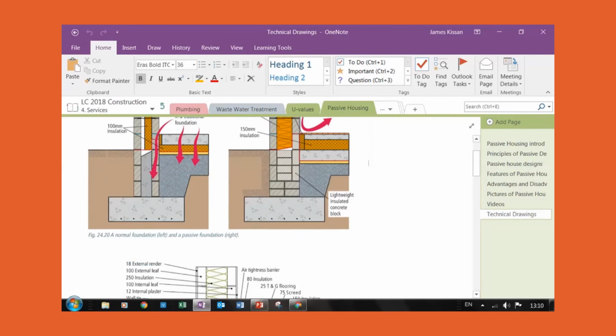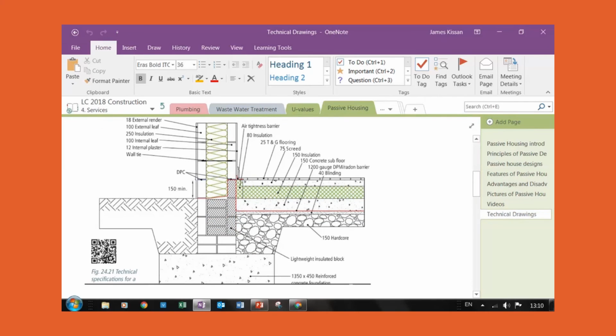Now, the last couple diagrams here are all showing all this detail. Now, these are all in your construction book. So what we have here, and it could come up in an exam that you're asked to do this. Now, what you have, insulation, you have levels of insulation here. The only thing that's really new is the way that the rising walls are built using these insulated blocks. And once you get up to this level here, the radon barrier is still the same detailing. Your concrete screed here, same detailing.